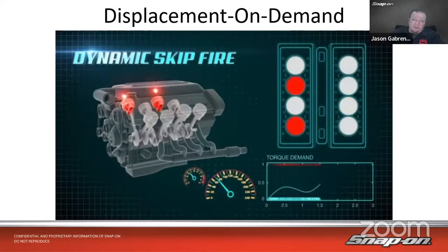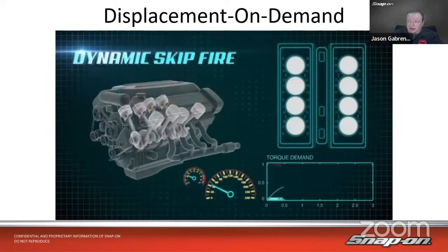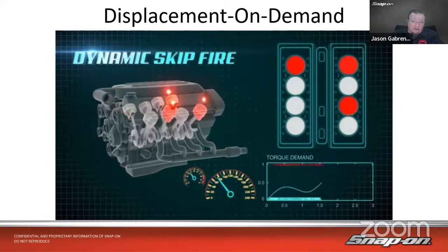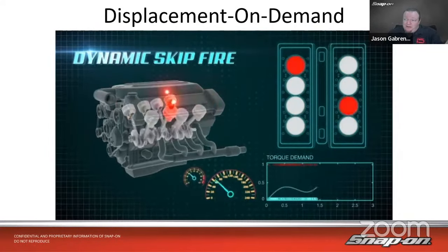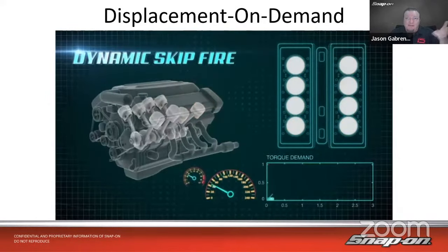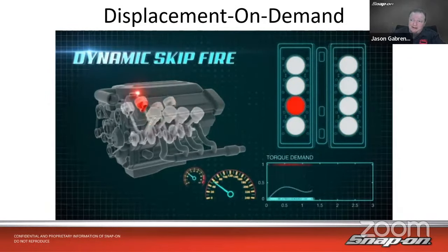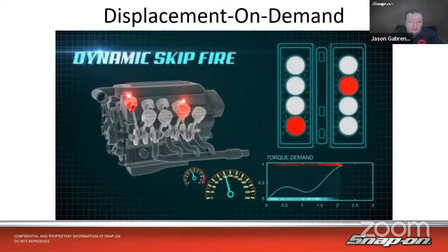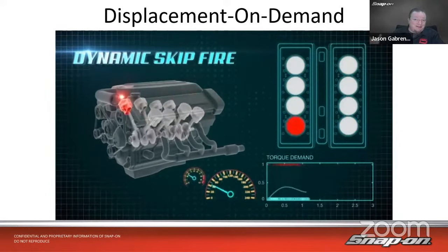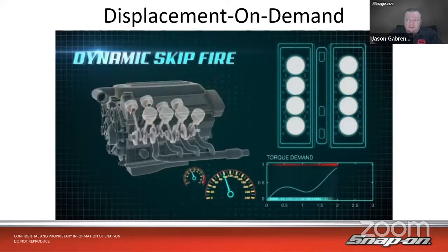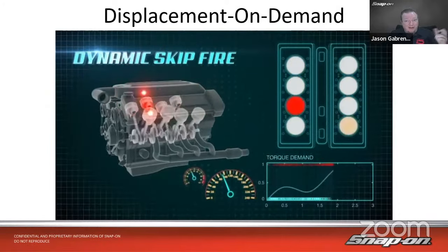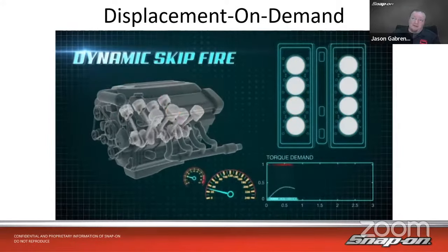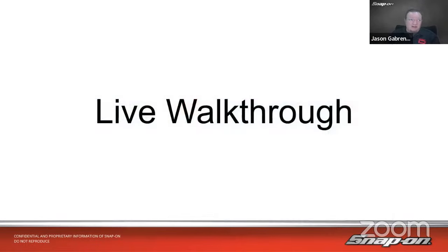And waiting around for one chip on one processor for one system, I think if you're going to cut out one system on a vehicle and either sell it or don't, that might be the one that the manufacturer wants to go with, right? So there are some out there. Just FYI, you may run into one of those at some point. You think it's got a problem, maybe a drivability problem related to the displacement on demand system, but it's not because it doesn't have it, although it's supposed to, just because of the year range. Don't always trust that year range, is what I'm trying to say, because there may be vehicles out there that do and maybe vehicles out there that don't. All right, so let's look at a few things on the tool.